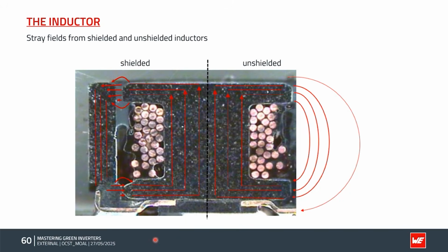Naturally, the shielded inductor is much better because it's got a lot less radiated field on the outside of the component, so less likely coupling into tracks or other components or boards.